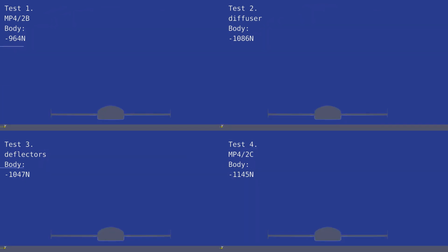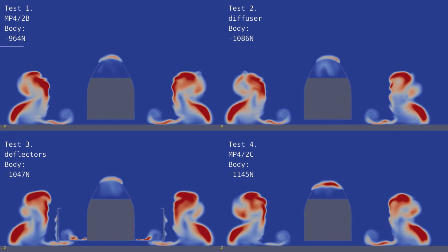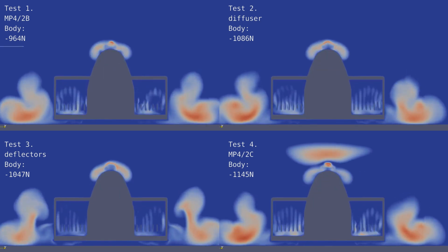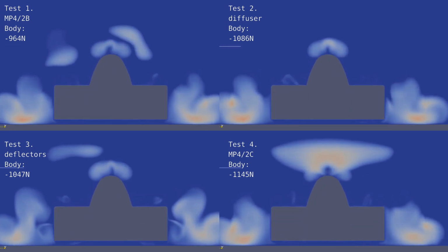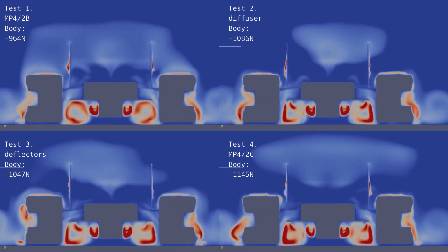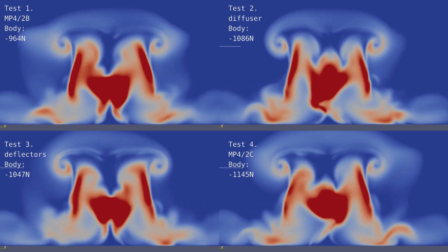The Kinetic Energy X movie has been important for identifying the turbulence. This is probably going to be the last time I use this tool, as it tends to be only useful for identifying the changes in efficiency of components. With downforce becoming more dominant and the wheels the most draggy component, understanding the aspect of drag is secondary.